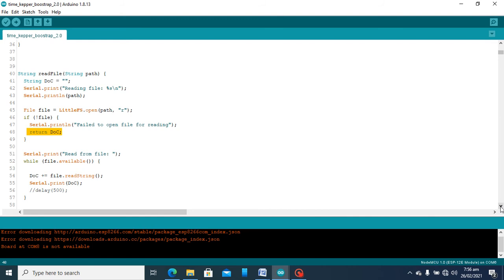So now it sends the HTML file as a string. And I'm using Bootstrap in this case. The Bootstrap file is too large to open. Anytime I try to open the Bootstrap file and store it in a string, the ESP8266 resets itself and the whole thing will be scattered. Instead of doing that, what I did is send them as files instead of opening them as a string. So I send them as files, and they can work properly.